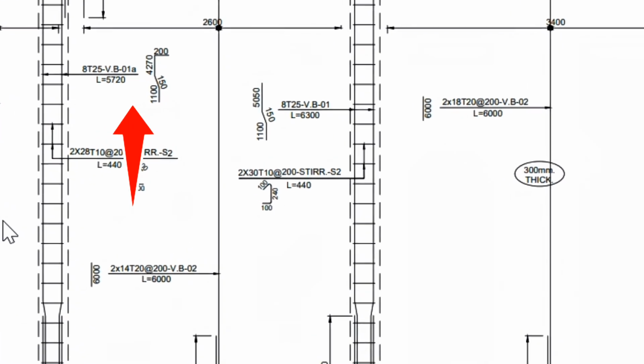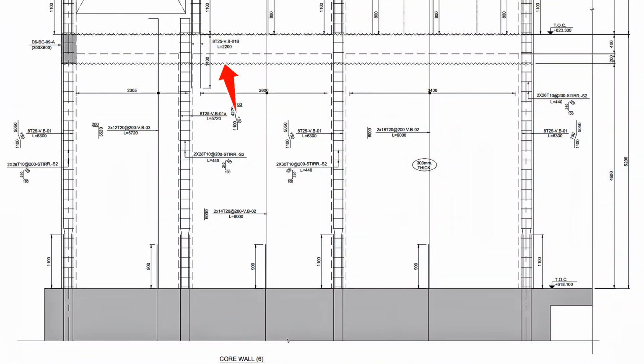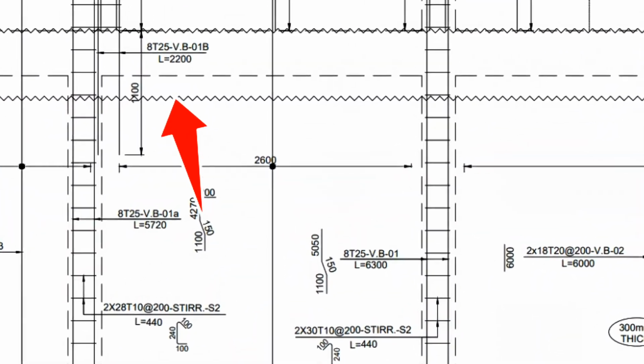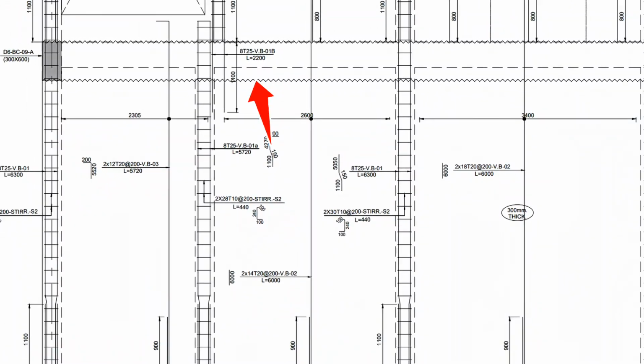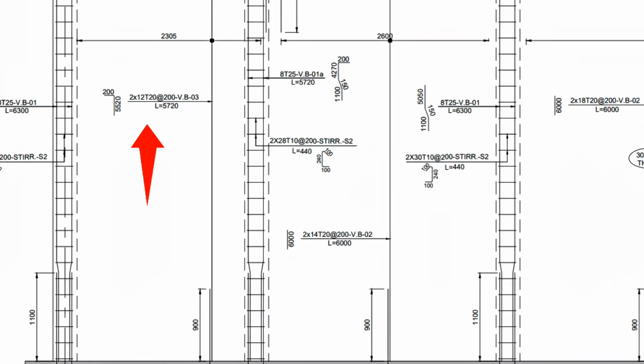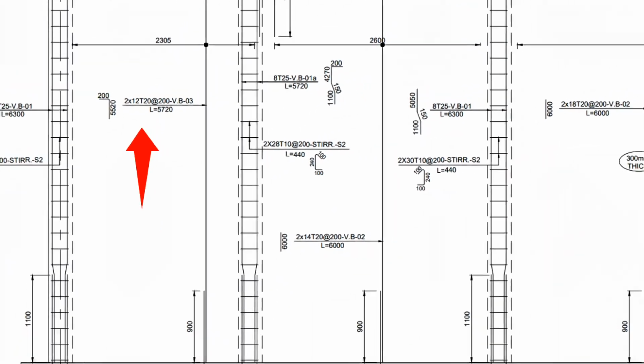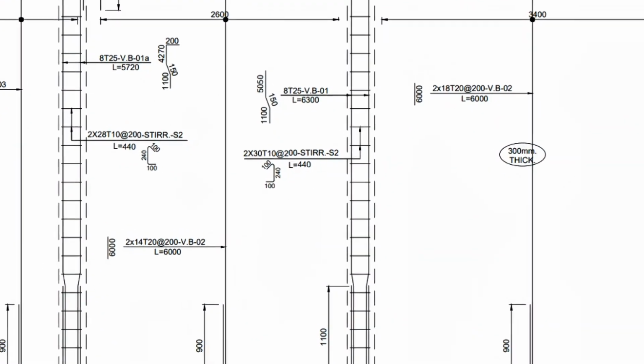Core Wall 6 section elevation BB, vertical reinforcement details indicate that vertical L bars will be used for 1 column consisting of 8 pieces of 25 mm steel bars, because there is an opening at the top of level 1, requiring a new column to be created that allows steel bars to continue to the rooftop. The wall will also include 20 mm steel bars, which will also function as L bars. The dimensions of the steel bars are illustrated in the drawing.